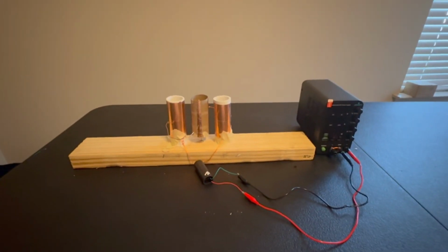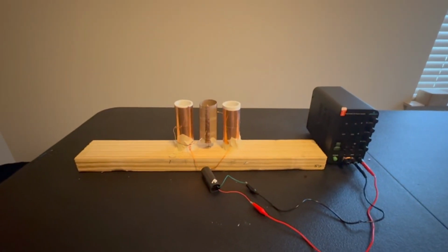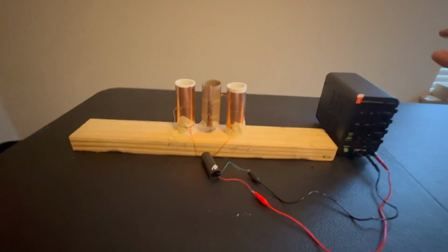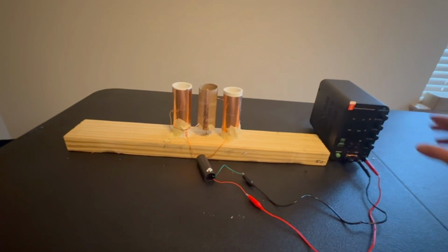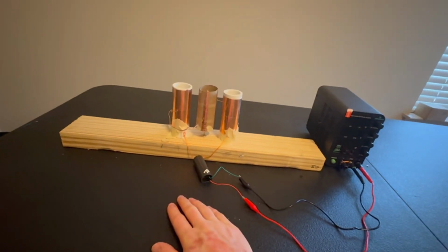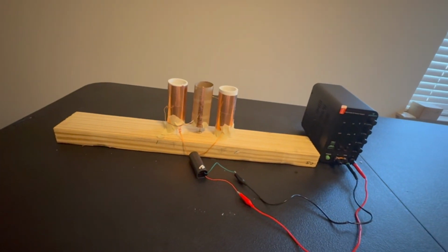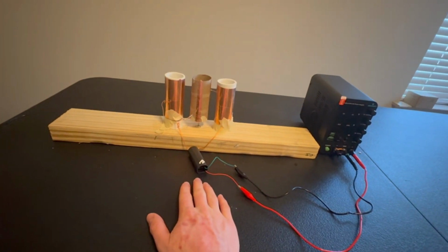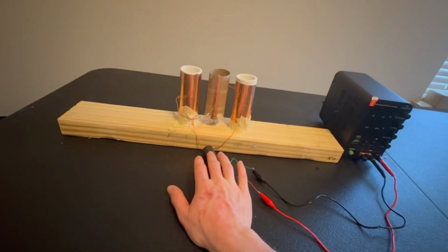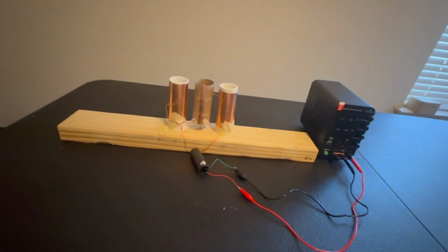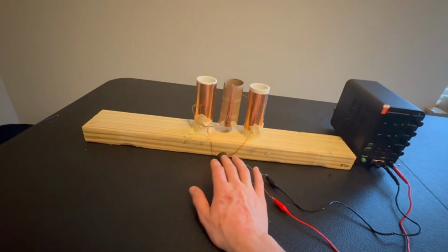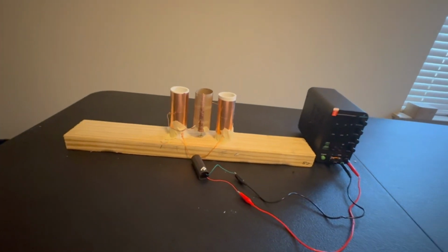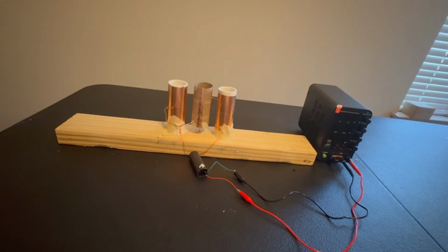Hello, my name is Brian Casada, and now we will be doing our demonstration of our electrostatic motor. Here we have a power supply, which will be set to 2.6 volts for input, and a pulse generator, which will help step up that voltage to 60 kilovolts. You can find these relatively cheaply online, and we did tests and confirmed that this is outputting approximately 60 kilovolts, although what runs through the system might be slightly less due to resistance and other factors.